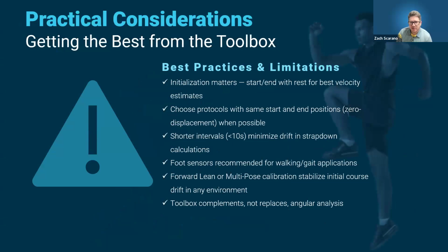Now, there are a few practical considerations to keep in mind. So initialization matters. Strap-down integration requires periods of rest at the start or end to correctly initialize velocity. Starting and ending the movement interval in the same horizontal and vertical position can also be used to mitigate integration errors. And shorter analysis intervals, under 10 seconds, can help minimize drift, especially for non-foot segments.